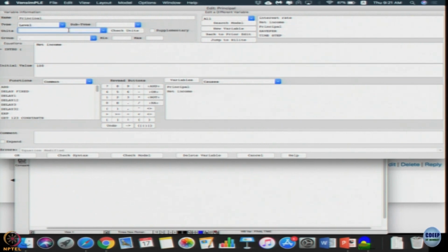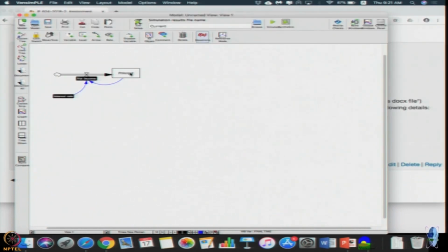The main thing we need to write here is the units, so that I can do the units check. Let us define it as rupees, RS. That is the only thing I added, along with the initial value 100. I click OK, this became white, it means some equation is put. Whether the equation is right or wrong, it will not tell, there is just something written there.